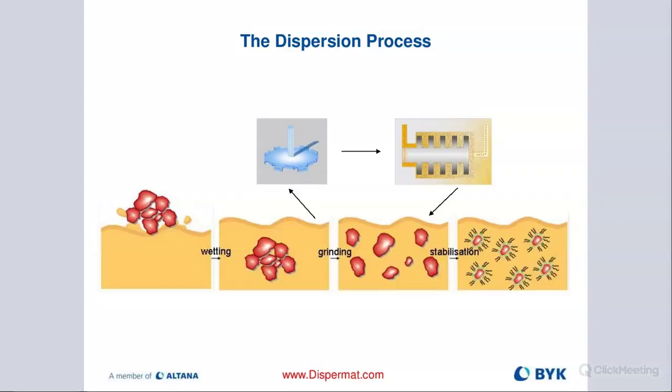This slide here lays it out more visually, I think, from the dispersion process point of view. We always start out with a dissolver using a Cowles blade or an immersion impeller, some people call it. That's a blade with teeth. We're putting in energy, high tip speed, and basically we're wetting our material and then breaking up these agglomerates and turning them into aggregates. Once we reach about 10 to 30 microns of particle size is when we actually start the fine grinding or milling process. You can see there is a rotor right there.